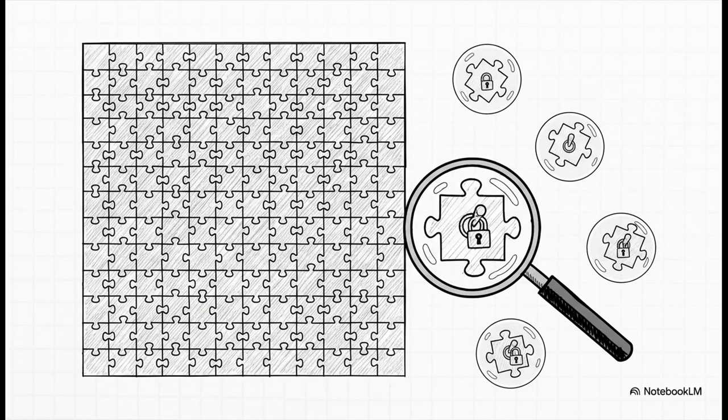Then, we take it a step further into microsegmentation, and this is where Zero Trust really shines. We aren't just chopping up networks, we're applying granular rules down to specific assets and users. This means you're strictly separating your standard control systems from your safety mechanisms, and even enforcing read and write permissions on individual data tags within a single controller.